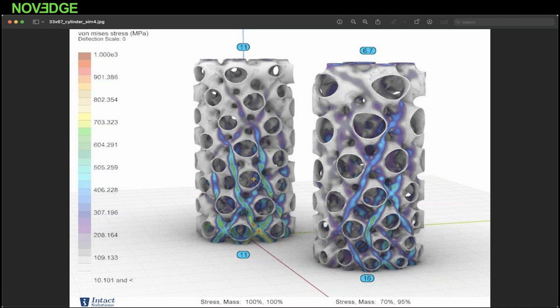So this output here is made inside of Rhino with Grasshopper on a cylinder where we apply force from the top. And we have here, as you see, a constant density on this cylinder. And you see when we press on it, we have an accumulation of stress on the bottom part. And then just very naively, we lessened the density on the top and made it more dense on the bottom.